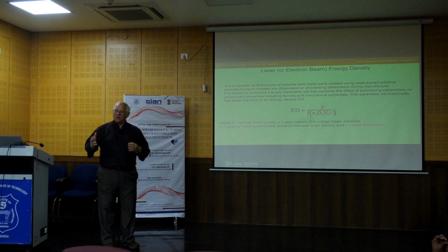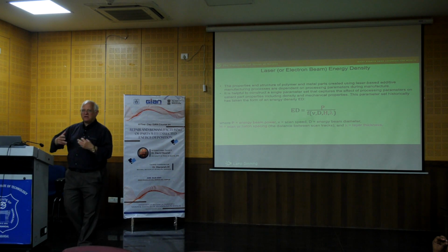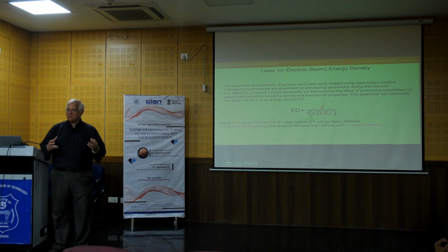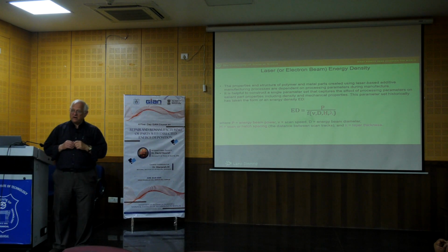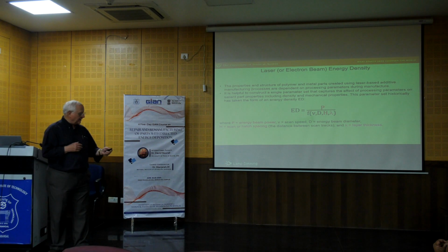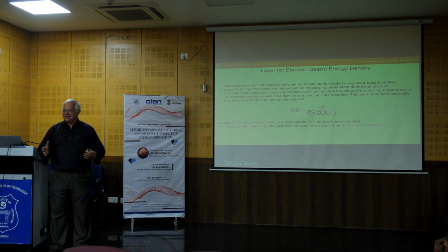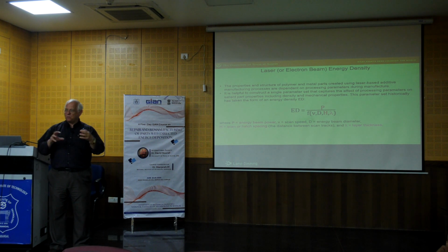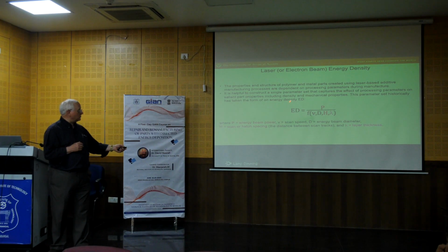And again, other than helping us to set the machine properly, it also helps us understand the interrelationships, because if I know the function, maybe I can increase the scan speed and build parts faster, but it tells me what other parameters I need to change and by how much in order to maintain the same energy density.